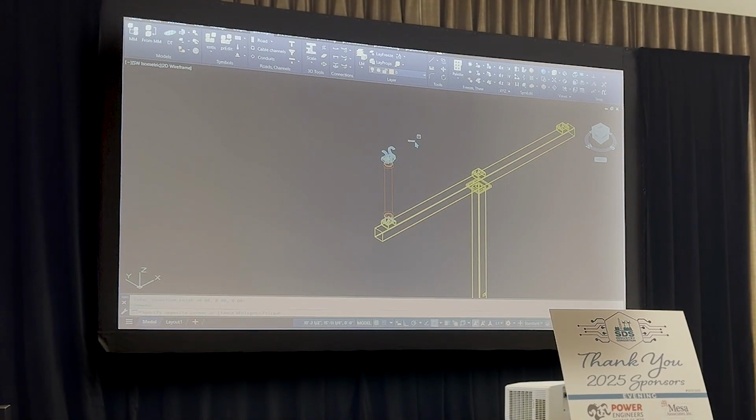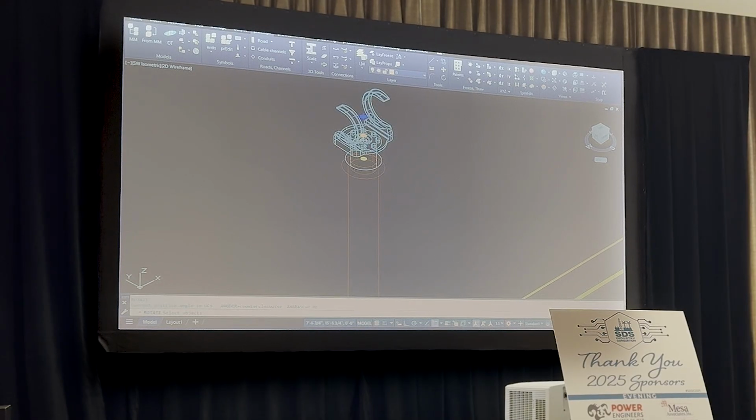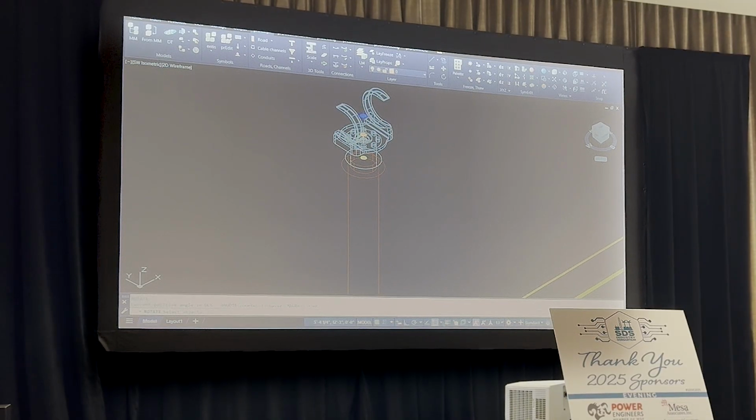Now you see this was rotated wrong, right? And this is where the power of AutoCAD kind of comes in. Real complicated commands here. I want to rotate that, so I'm going to type rotate. Then I can snap to these points and use those as centers of rotation. So, kind of hard to do this when I have to draw my mouse and it keeps falling back down.